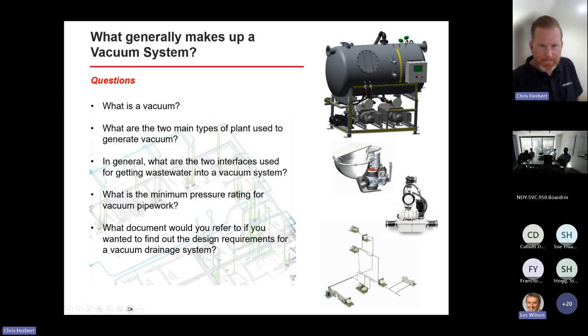I've just got another one for you, Chris, actually. Yeah, absolutely. With the small bore and your speeds of 10 to 15 meters a second, small bore, but you're going to increase your frictional loss. So how does that work in? I know HDPE or PE plastic's got very low frictional loss, but you're still going to pick up a hell of a lot of friction. How does that affect the system?